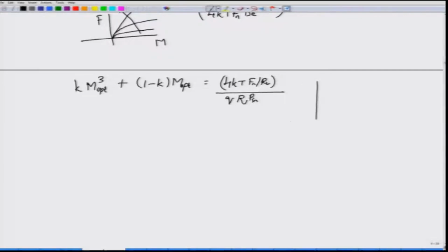You can see that if you plot the optimum value of m for different incident optical powers, measured in dBm, the optimum value of m decreases as incident optical power increases. This happens for k equal to 0, and these are the values for increasing k. Remember that k is the ionization parameter dependent constant. So, this is for the APD.